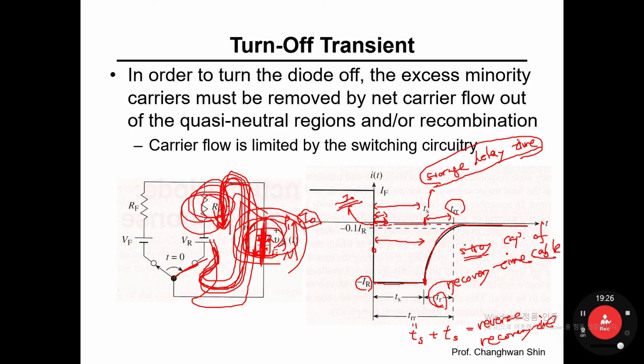Unwanted and unidentified capacitance components would significantly affect T_RR and T_R. So this part would be very dependent on the measurement system. People don't want to be confused by the measurement system that each person is using, so people use the storage delay time as a standard figure of merit.